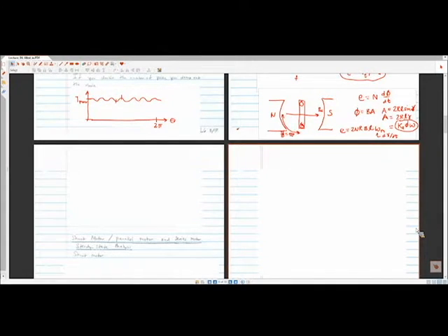So you can buy a variety of different motors. There's really a few set ways in which they're wired up, and then that gives you the diagrams. We're going to only focus on 4 of those, and really only 2, and we're going to spend a lot of time on it. So the 4 of them are the separately actuated motor, which we're going to talk about first, and then we're going to have parallel, series, and also permanent magnet DC motors.